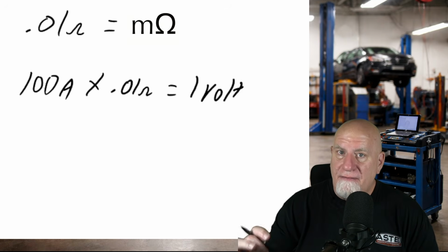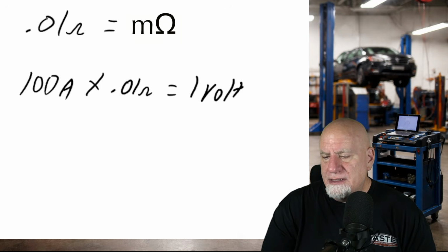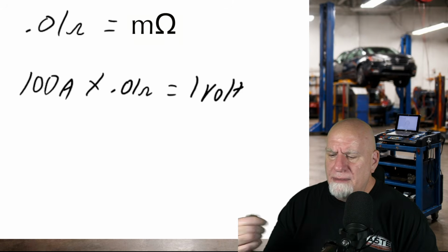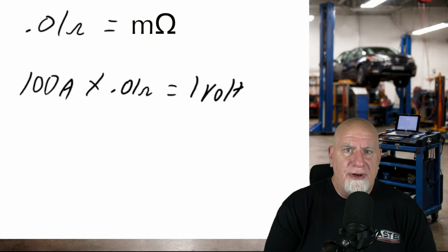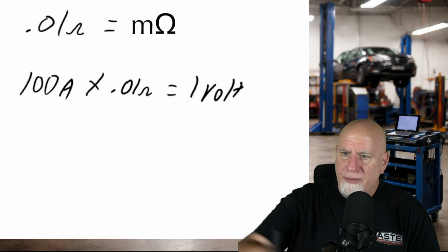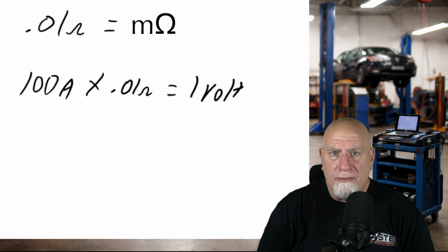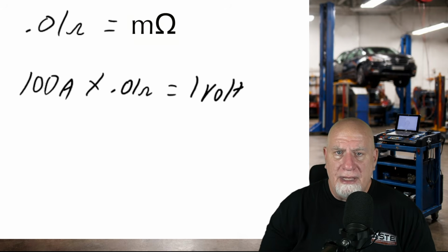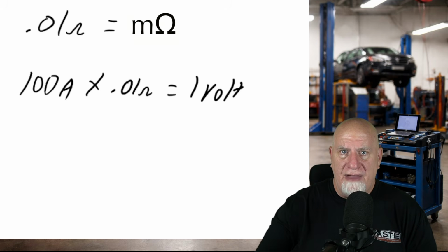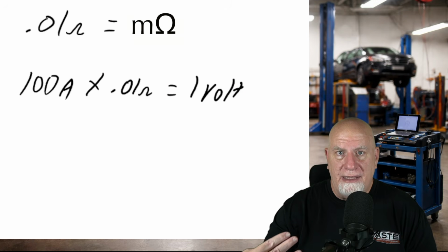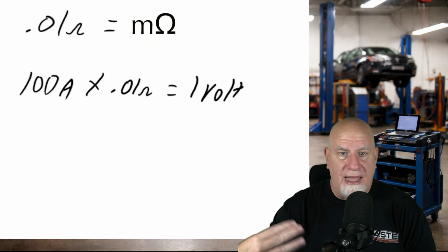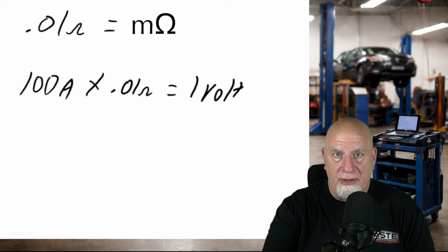That can create a lot of heat, which can cause a fire in a hybrid or an EV vehicle. So when it comes to working on hybrid and electric vehicles, I did some training 2 weeks ago, and one of the things that they were really tough on was torquing the connections between the drive motor and the inverter, or the cables between the drive motor and the inverter and the cable that goes to the drive motor, making sure that those are torqued properly and that they have a nice snug fit.